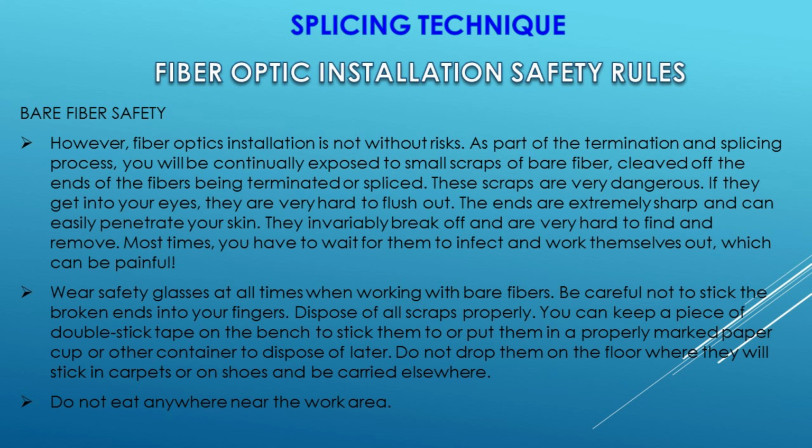Wear safety glasses at all times when working with bare fibers. Be careful not to stick the broken ends into your fingers. Dispose of all scraps properly. You can keep a piece of double-stick tape on the bench to stick them to, or put them in a properly marked paper cup or other container to dispose of later. Do not drop them on the floor where they will stick in carpets or on shoes and be carried elsewhere. Do not eat anywhere near the work area.